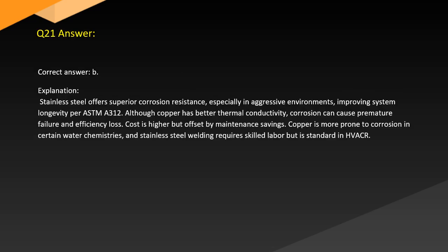Correct answer: B. Explanation: Stainless steel offers superior corrosion resistance, especially in aggressive environments, improving system longevity per ASTM. Although copper has better thermal conductivity, corrosion can cause premature failure and efficiency loss. Cost is higher but offset by maintenance savings. Copper is more prone to corrosion in certain water chemistries, and stainless steel welding requires skilled labor but is standard in HVACR.